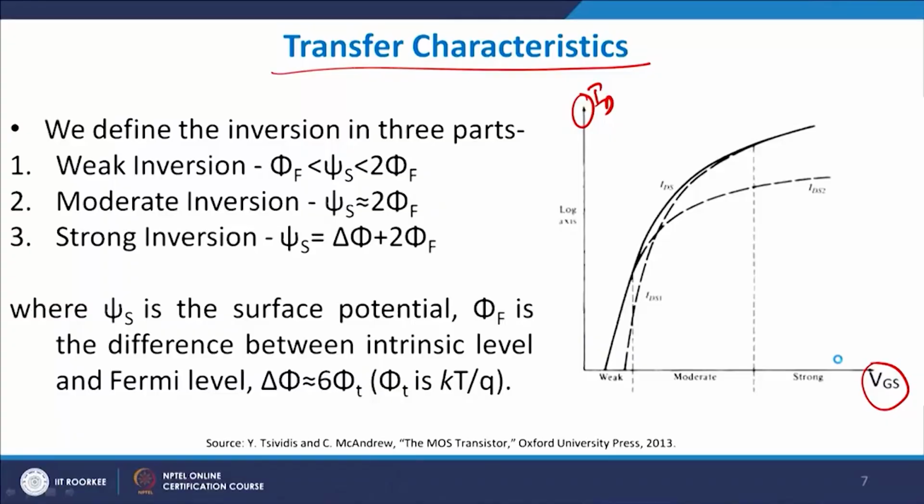When the gate voltage crosses the threshold voltage, you will have a large number of charge carriers at the silicon dioxide interface, and as a result you will have an on state available. Typically, if you look at this graph here, this is my threshold voltage, VTH.